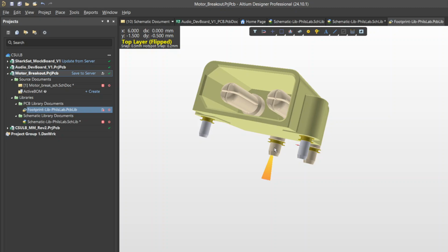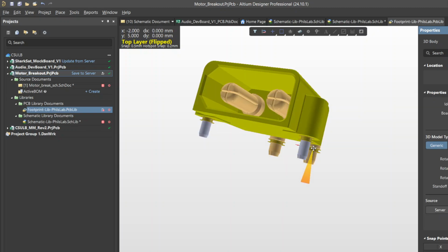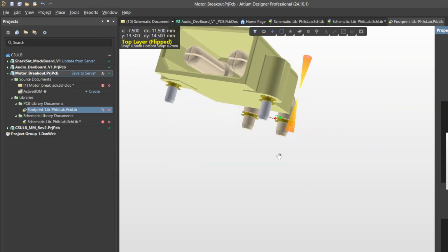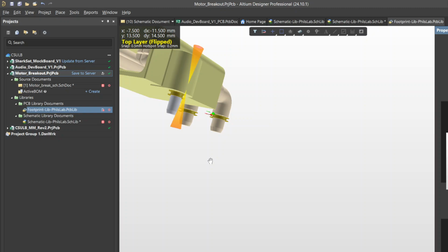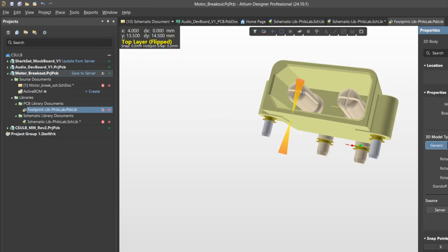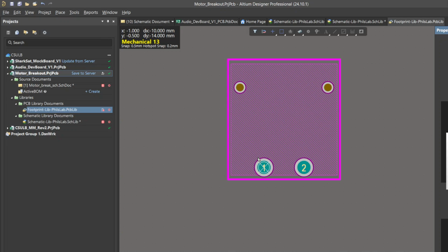So I just want to double check by selecting. No, it's just going to select the whole thing. But I believe that one is connected to the one on the right and that one's connected to the one on the left, which adds up to here. So, yeah, that would be bad if we accidentally hooked up the positive to this one and the negative to that one. When we plugged in our system, everything would get fried because we did reverse voltage.